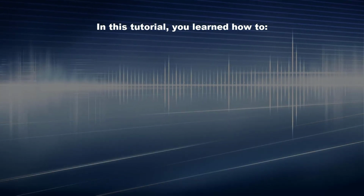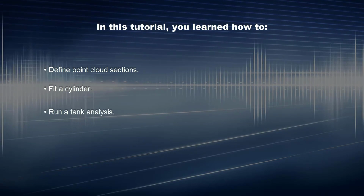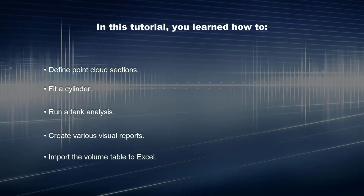In this tutorial, you learned how to define point cloud sections, fit a cylinder, run a tank analysis, create various visual reports, and import the volume table to Excel.